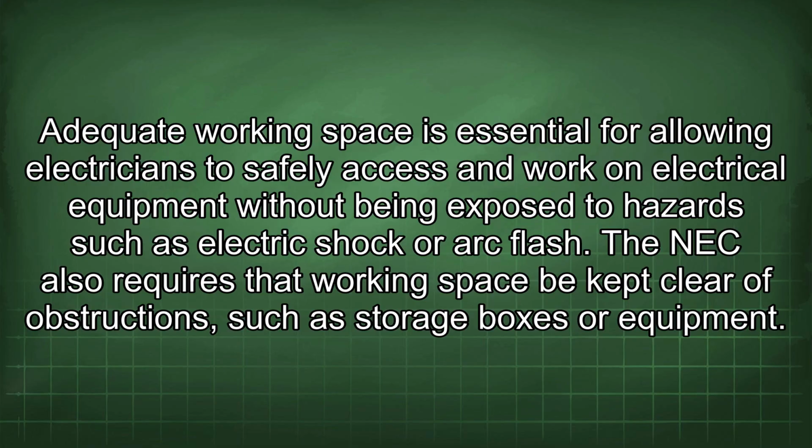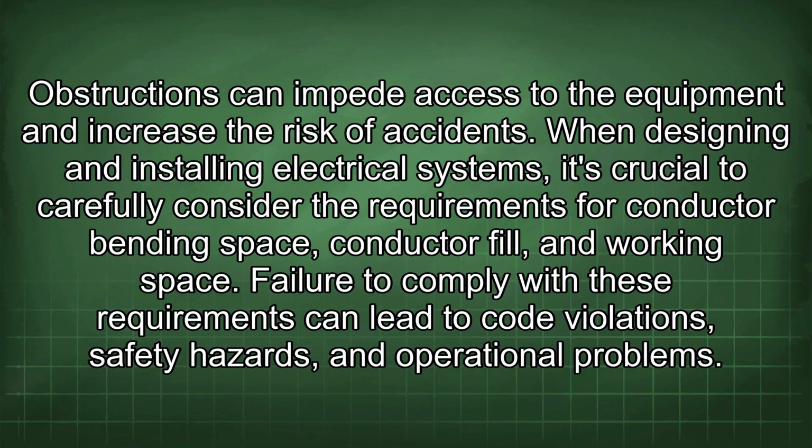The NEC also requires that working space be kept clear of obstructions such as storage boxes or equipment. Obstructions can impede access to the equipment and increase the risk of accidents. When designing and installing electrical systems, it's crucial to carefully consider the requirements for conductor bending space, conductor fill, and working space.